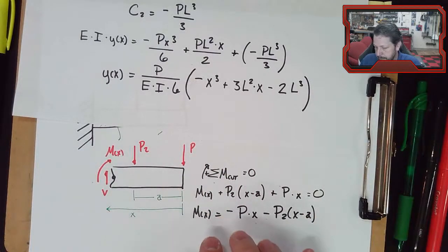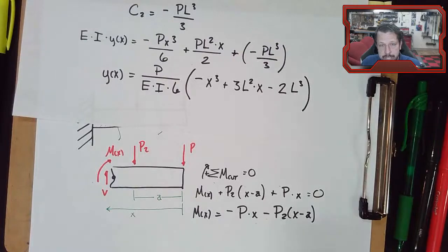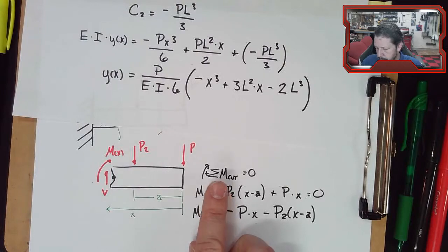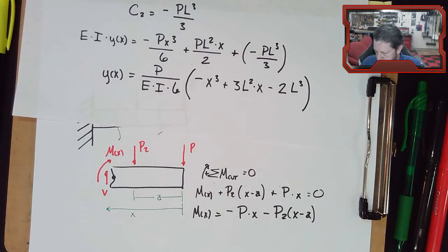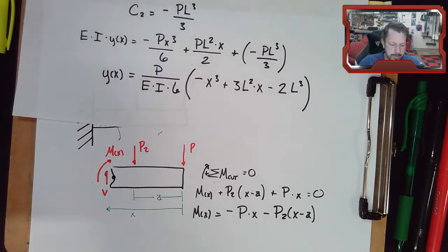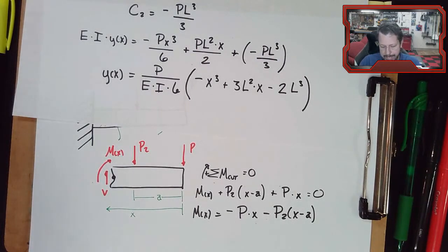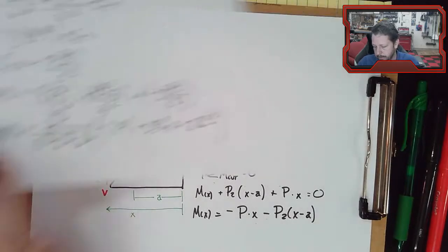But that is one way to calculate the deflection, or to plot the shape of the beam from one end to the other, is to do something like this. You could do some more iterative methods where you have this bending moment calculated in a bending diagram or something like that. Maybe you could do it that way. But this is how the equation of the elastic curve is derived to use the charts. Now, most of the time, you're just going to use those charts, and you're going to figure out ways to combine them together